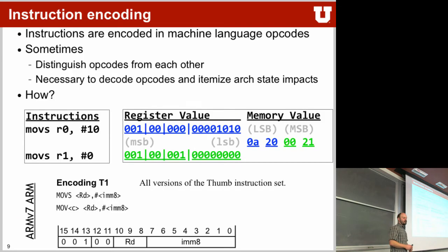We have seen this before, instruction encoding, how it works, right? Every instruction in assembly gets turned into bits, those will be stored somewhere in your memory, and then your microcontroller will start reading them out and start interpreting what they mean. And the ARM tells us what each bit and byte actually means with respect to which function will be executed. In here, what we see is a move instruction, and it's actually a small 16-bit move instruction.